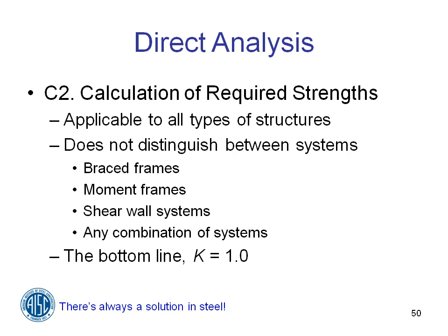The direct analysis method is applicable to all structures. It doesn't distinguish between brace frames and moment frames and shear walls. You can use the direct analysis method for arches. Any structure you can come up with, you can use the direct analysis method. The bottom line, as I've said before, is that K is equal to 1.